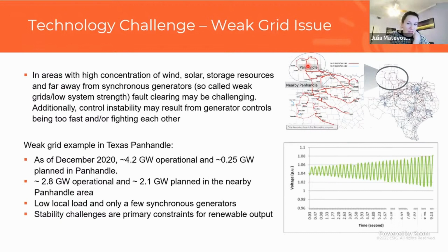So what I'm trying to do now is to motivate ERCOT. We're already starting a study now with ESIG, the company I work for now, to look at benefits of grid forming inverters for the ERCOT system. So we are hoping we can show benefit, especially in these weak grid areas, and to say that if these batteries that are currently in the interconnection queue and going into weak grid areas were grid forming instead of grid following, there would be a benefit. Then maybe the next step would be ERCOT will either incentivize or require grid forming capability.